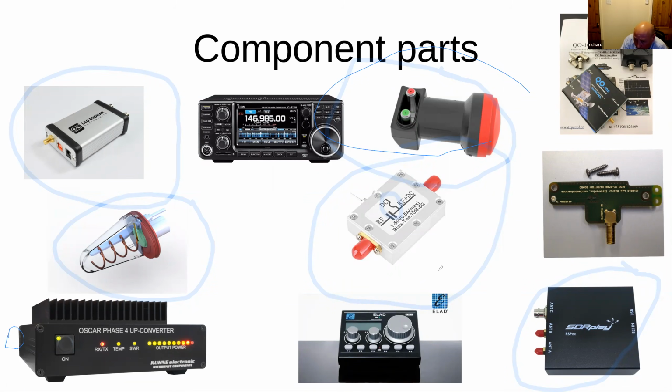Where was I going from there? So once I'd been playing about with this LNB, I decided I wanted to go for a decent GPS locked LNB, and the one that I went for is this one, from a company called DX Patrol. So you've got 2 ports. You've got one which is for the actual 739 megs output, and then another one which is for your GPS discipline, for your 24 megahertz reference clock.